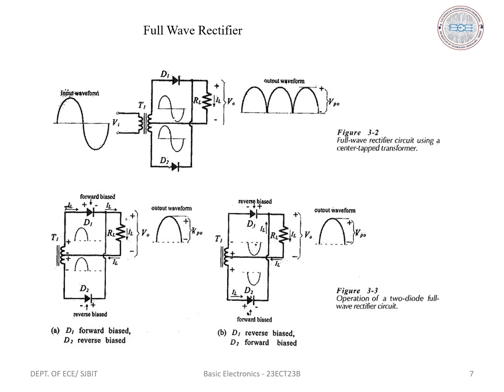The advantages of a center tap full wave rectifier are that the ripple factor is less, efficiency is high, and DC output voltage and load current are twice compared to the half wave rectifier. Next, some disadvantages of this center tapped full wave rectifier: the diodes used must have high peak inverse voltage, it is difficult to construct and locate the center tap on the secondary windings of the transformer, and the last disadvantage is that the output voltage is half of the secondary voltage.